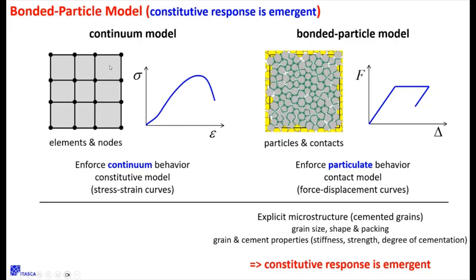And these are coupled, so a time step in one is the same as a time step in the other. This guy deforms, it moves the edges. The edges push against PFC. PFC builds up force. The force then gets applied as a boundary condition to the boundary. And so everything is in synchronization. We end up having full coupling. Does that kind of make sense? Yes. Okay. That's essentially what we do.